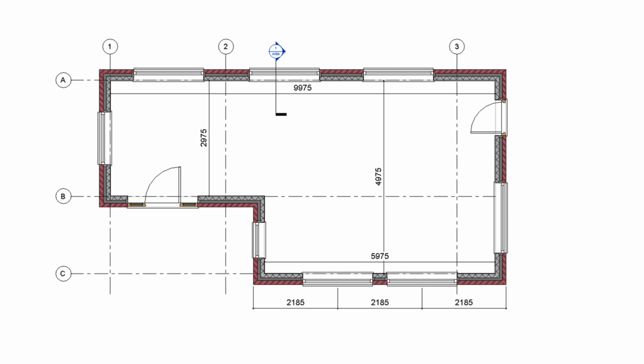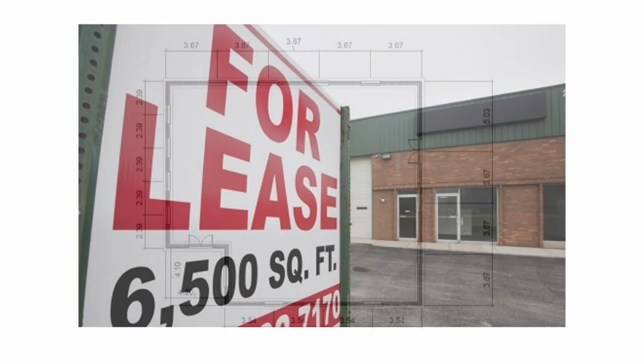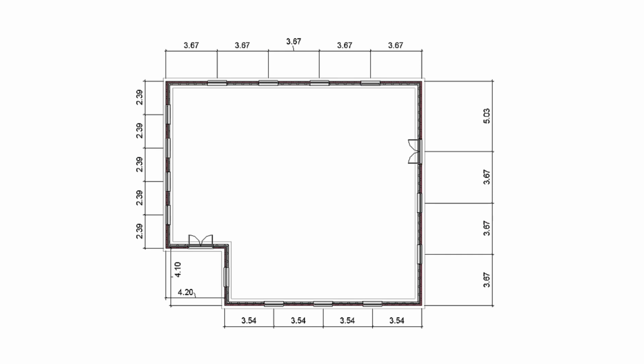In nearly every case when looking at drawings we are given the internal dimensions. This is because in the commercial world renters and tenants value room sizes and indeed whole buildings by their gross internal floor area. Sometimes we do get external building and room sizes, so we have to be able to use both of these to calculate the centre lines.